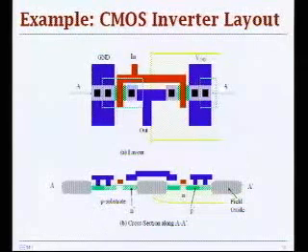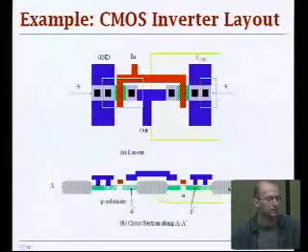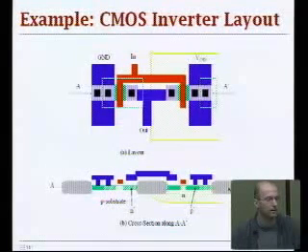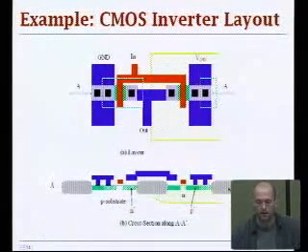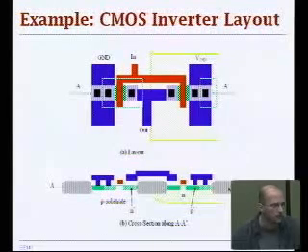Okay, any questions? Yes. You mentioned to have as many contacts as possible. Why don't you just make the contact go continuously through? That way it's wider and even less resistive. The question is, why don't you make a really wide contact that is less resistive? And that has to do, I think, with the mechanical stability of your structure. You normally don't do that.